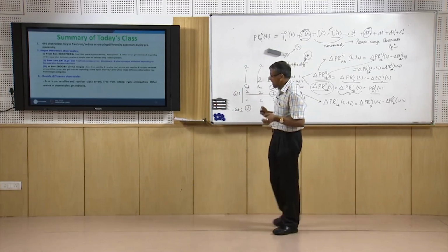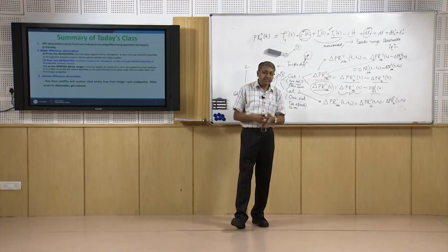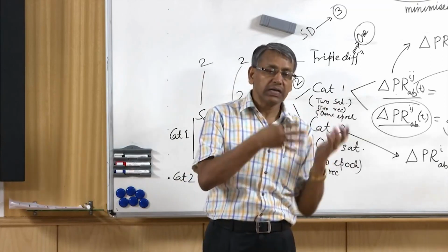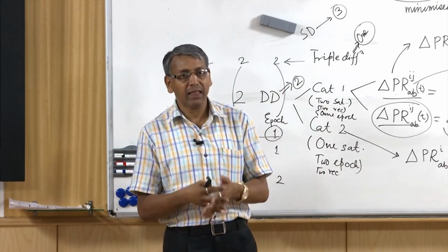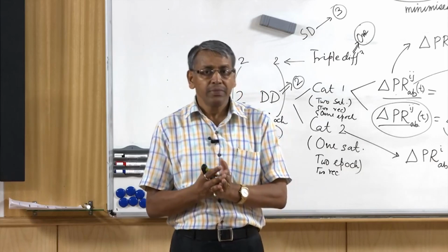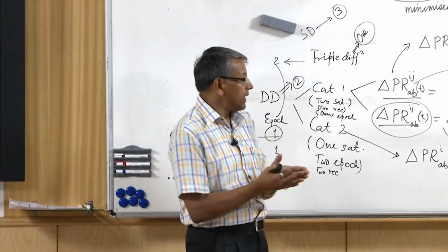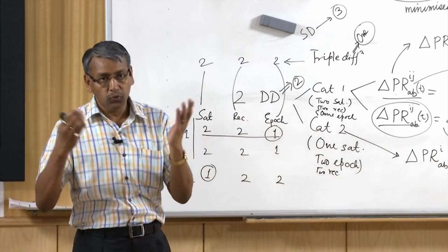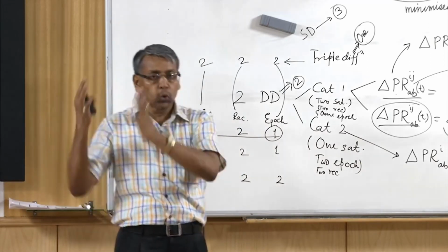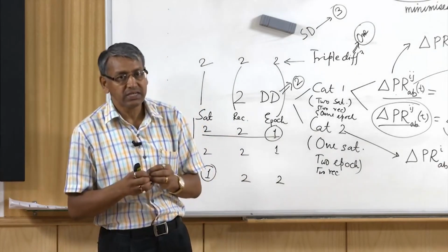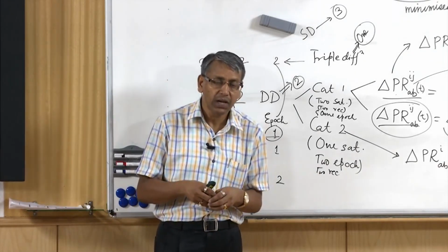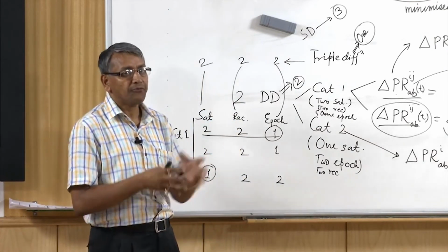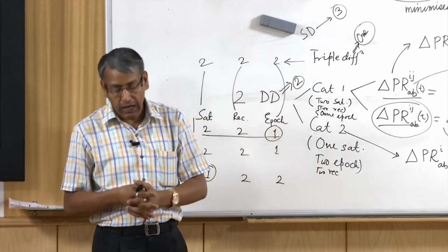The next variety is the double difference, which is the difference of the single difference observables, and there may be two categories. In the first category there will be observables coming from two satellites to two receivers, but we will consider observables at the same epoch of observation, and in that case we will be able to minimize the error from the receiver as well as the satellites.